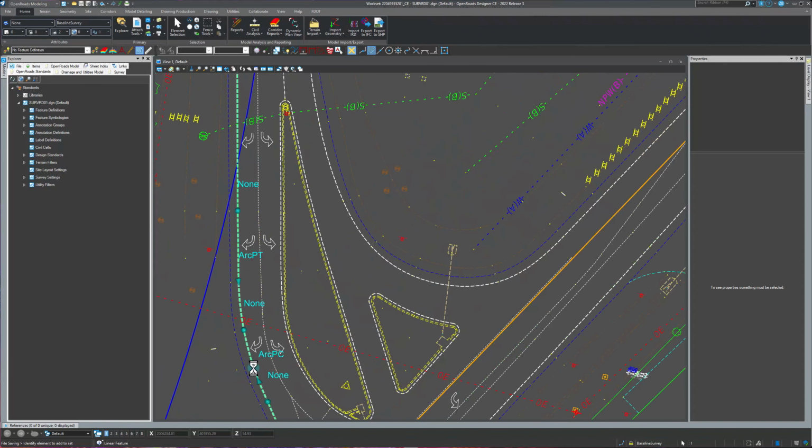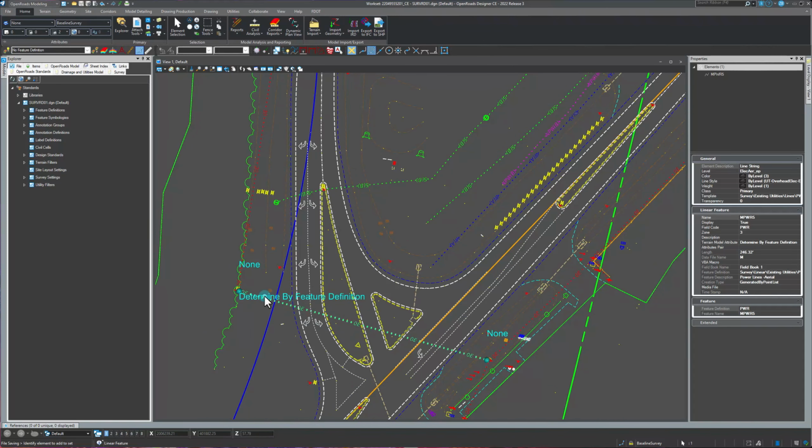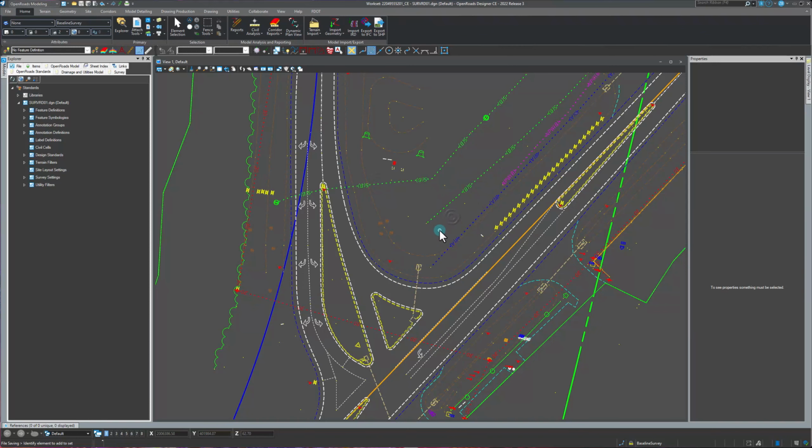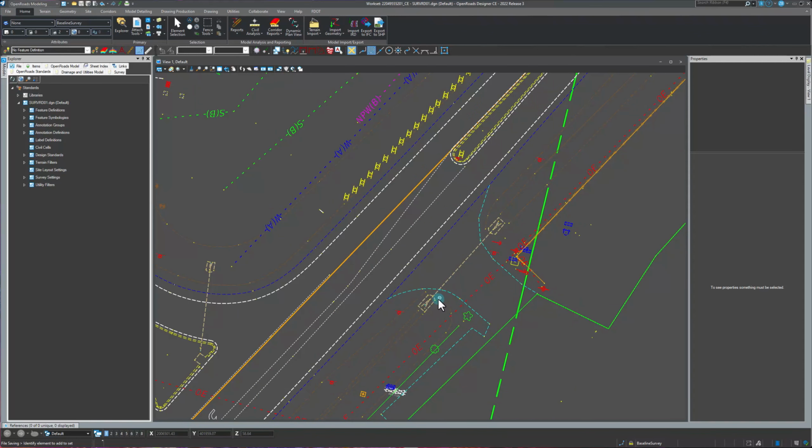So existing topography like the pavement and pavement markings, curb, things of that nature will go into a TOPORD01 file. Utilities such as this overhead electric line or this buried sanitary line, buried non-potable water line, those are going to all go into a UTEXRD01 file. And then our drainage will go into a DREXRD01 file.